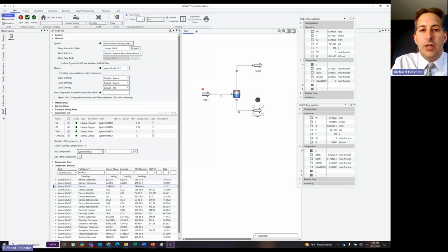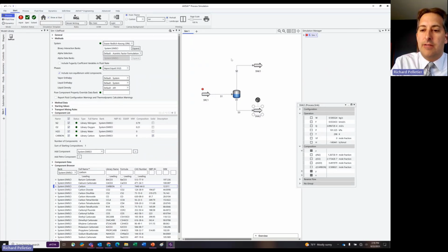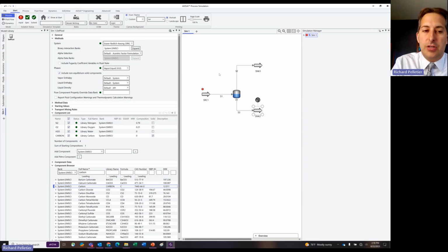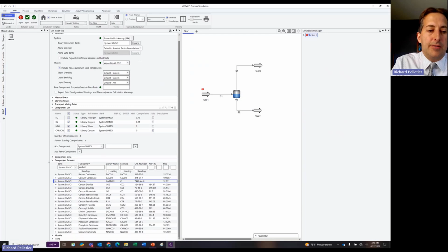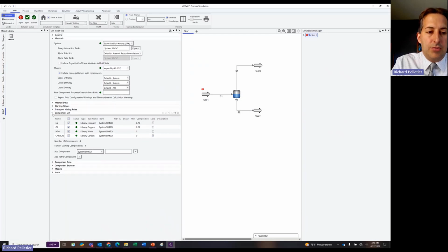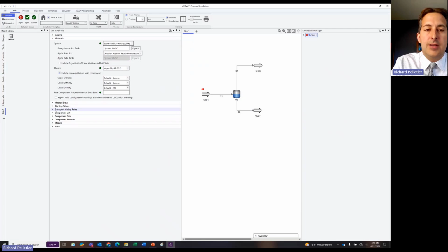Now, if you want to include the solid component into some kind of phase consideration, then what you can do is you can create a reaction submodel that tells it through equations in the submodel how to utilize the solid in relation to other components, how to perform some of these equilibrium calculations, or reactions, for example, like how to react it away or form it from other components.